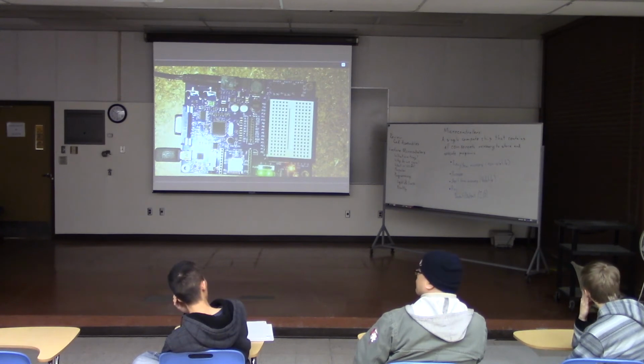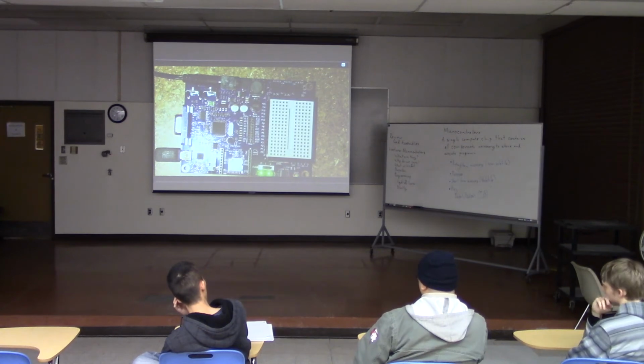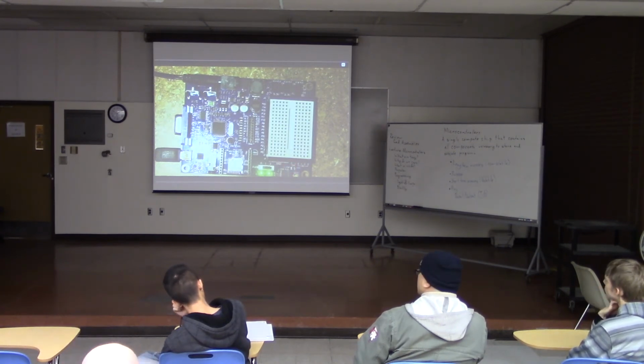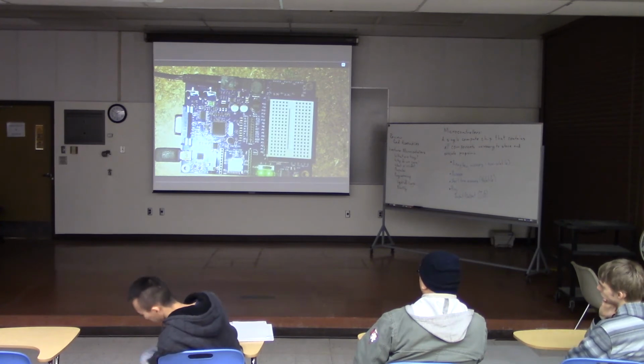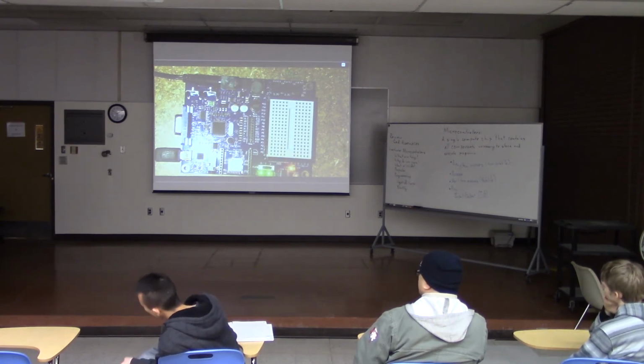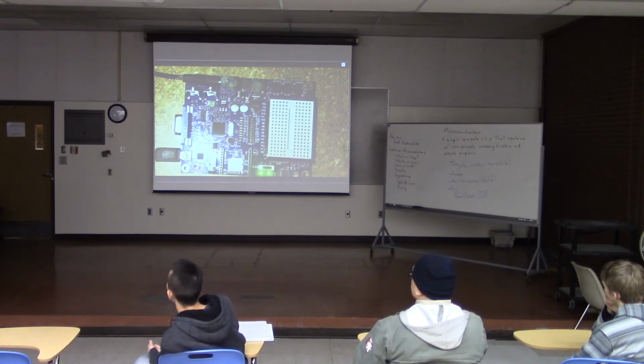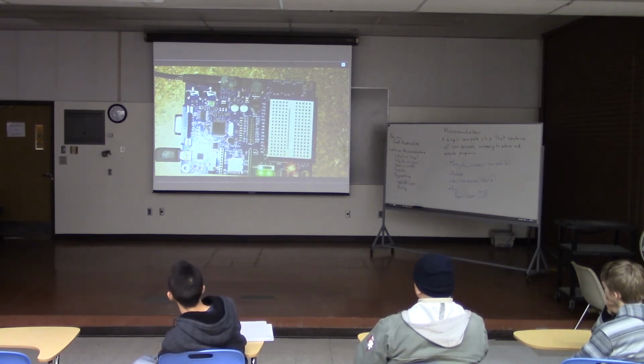It's possible to use this type of microcontroller to control much, much larger motors, but you need to add additional circuitry between the microcontroller and the motor to do that. So there are other chips that are designed specifically to do that. There are chips called MOSFETs or IGBTs that are specifically designed to have a very low power input that controls them, and then they are able to switch and turn on and off some very high power, high current applications.